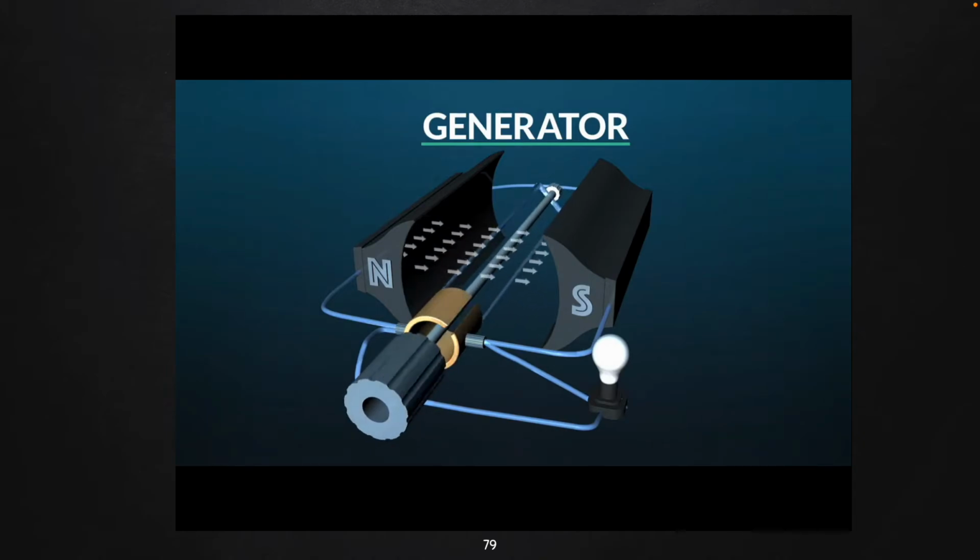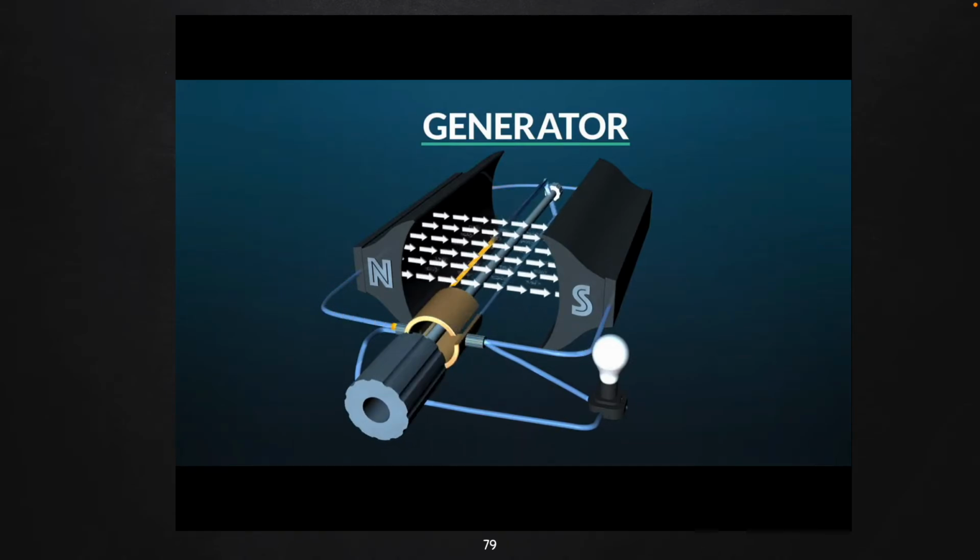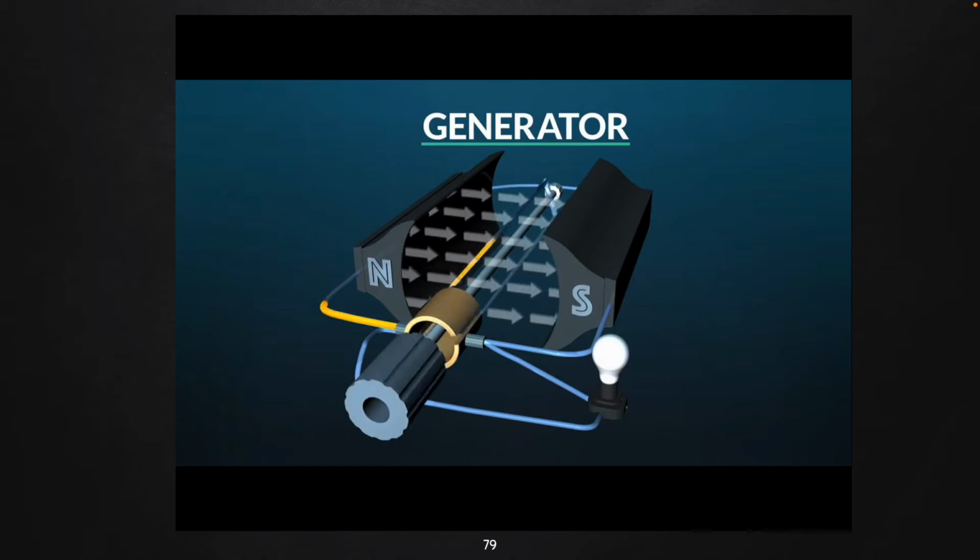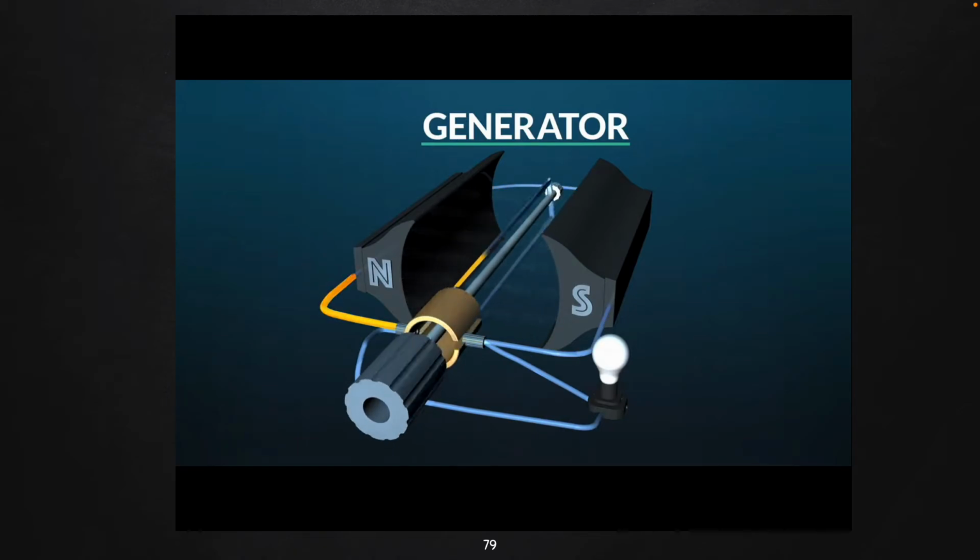There's a residual magnetic field within the stator that provides the initial push to start current flowing through the armature as it rotates. Some of the current produced by the moving armature flows to the stator, strengthening the magnetic field and increasing output. In this car, the excess current from the armature is used to power things like headlights and turn signals, as well as charge the car's battery.